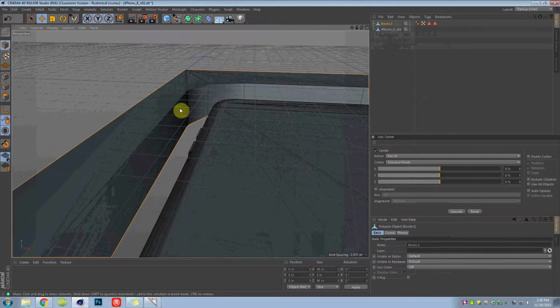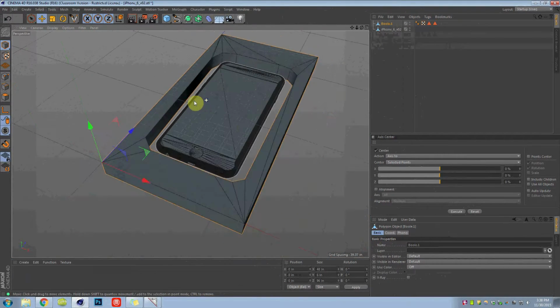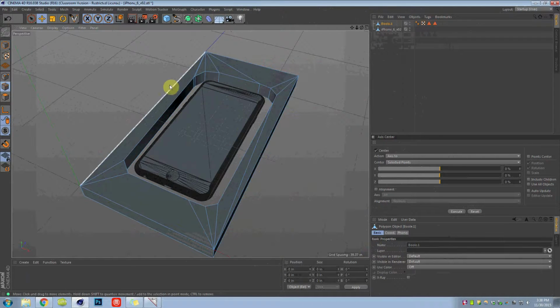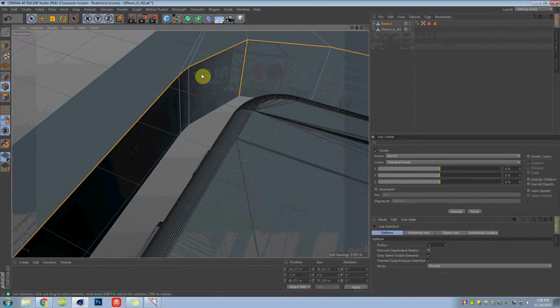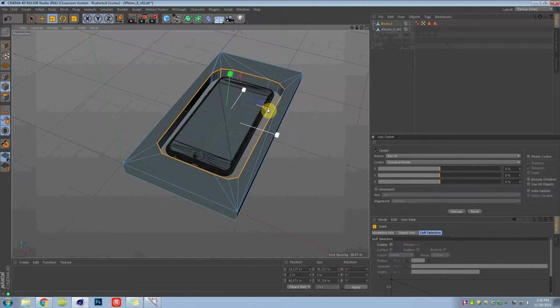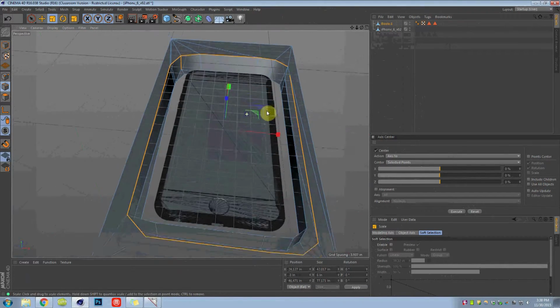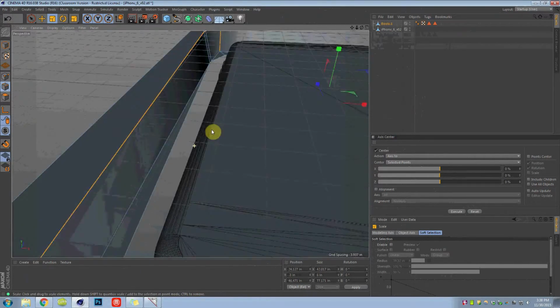Before I get to the lattice work, something you might consider doing is making this drop down a gradient to prevent the collet on the bit from hitting the stock. There's a couple ways to do that. One is select this ring of lines and just scaling them in one direction, like this. So then your lines come down at an angle, but obviously that gets weird.